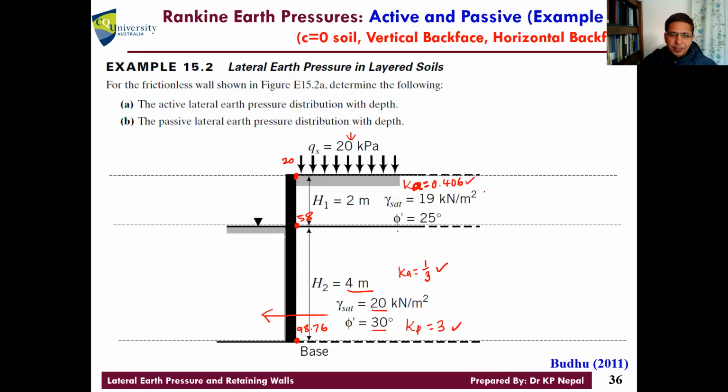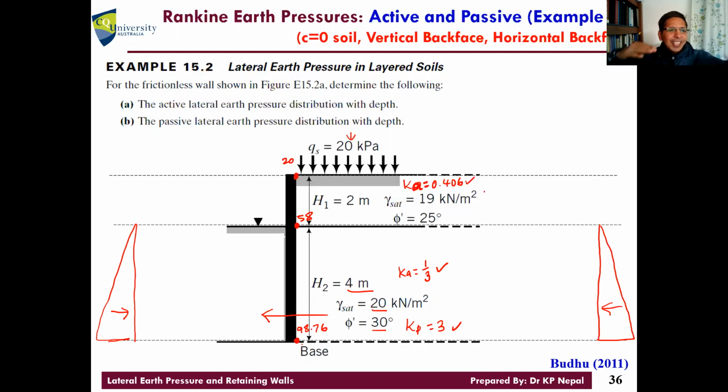Now, always don't forget this water. Can I draw water first? Because I forget that sometimes. This is the water pressure, right? Yeah. You see? And there is a water pressure from this side also, and it is equal and opposite. What happens? This pressure from that side, water, this pressure from that side, they cancel each other, right? They're balanced, both sides have the same water level. The pressure is the same, right? We may ignore this. I think this textbook has used that, but later on, we don't need that. If pressure is from both sides at the same level, that means it is completely hydrostatic.